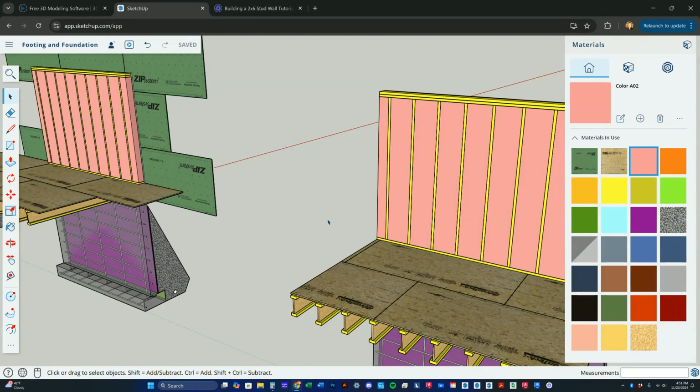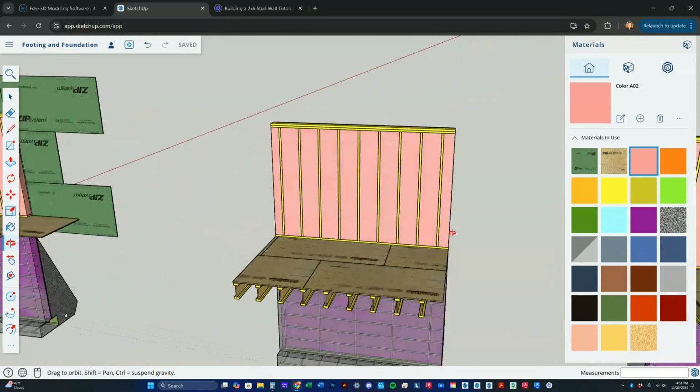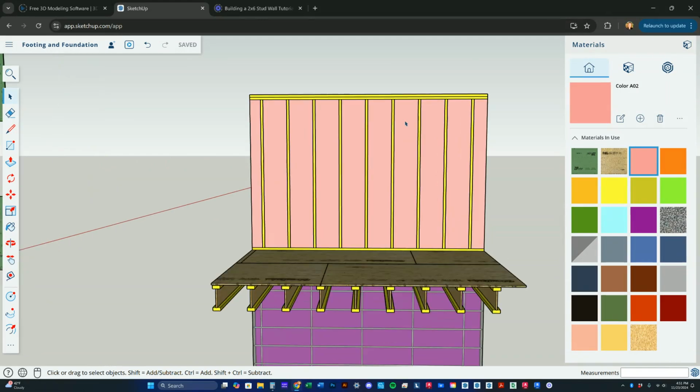Let me turn around if I can. There we go. And again, this is a 12-foot length of wall, and according to your assignment, you are going to put a 3'6" wide by a 5'6" tall window, rough opening into this wall.